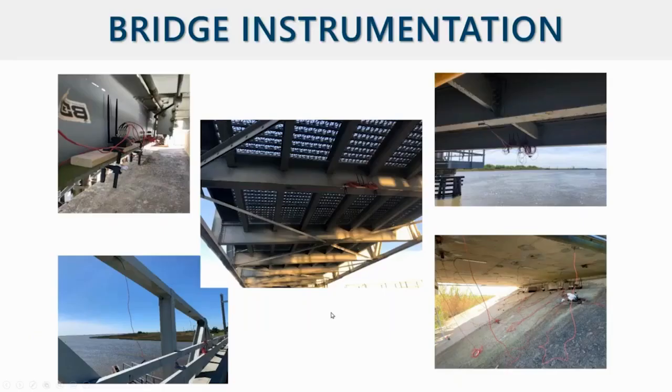We did a load test with the instrumentation. This is not the main purpose of this presentation, so I'll just go quick. You can see there, this is the end floor beam. In the middle floor beam, we applied the gauges at the top flange and bottom flange, and then connected to this. These are the wireless nodes, and they can transmit the data to the computer.